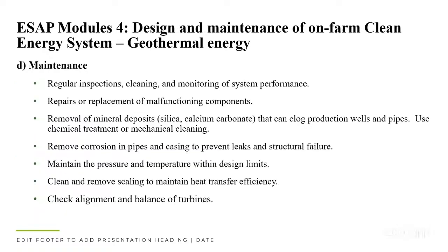So in terms of maintenance, as for the previous energy systems, we need regular inspection, we need to clean wherever we want to clean, and then monitor the system performance for the different components. We need to think of repairs where we have faults, especially in terms of the turbine, but also the generator used, and also looking at leaks, if there are any leaks on the piping or in the valves, and tightening some of the bolts to make sure that the system is really closed.